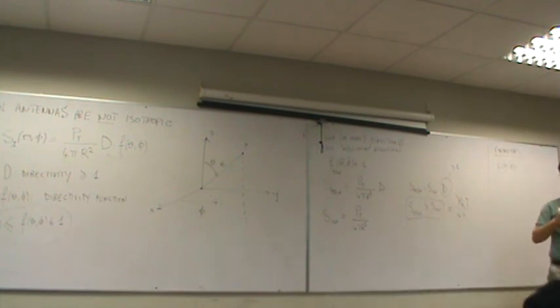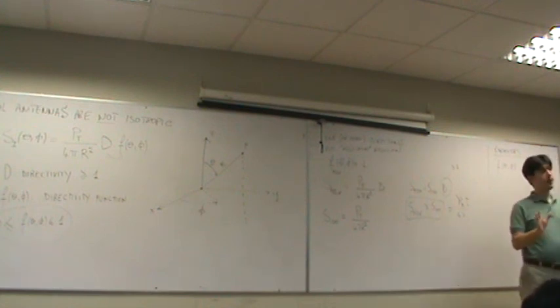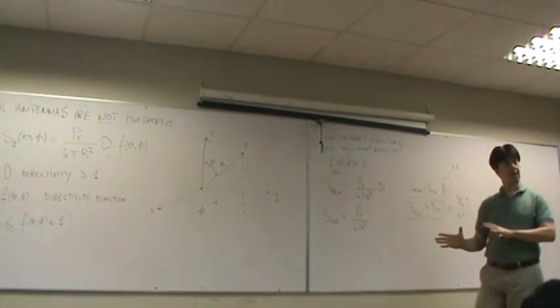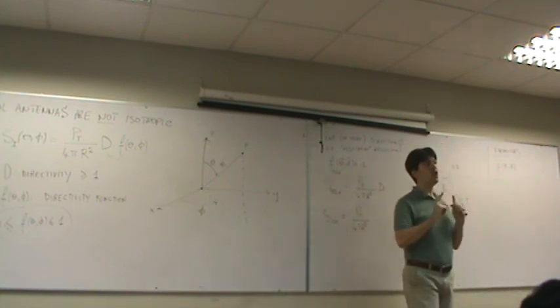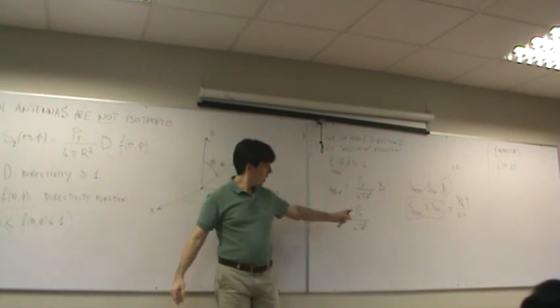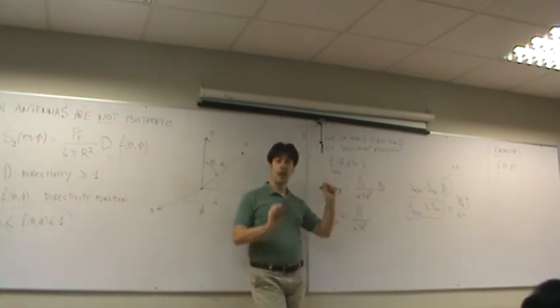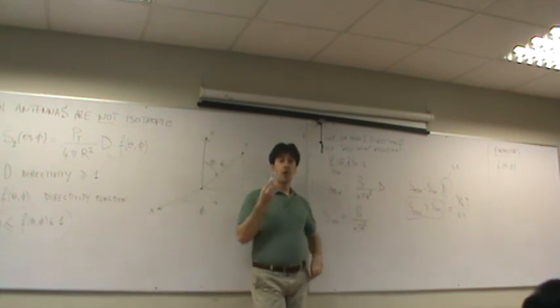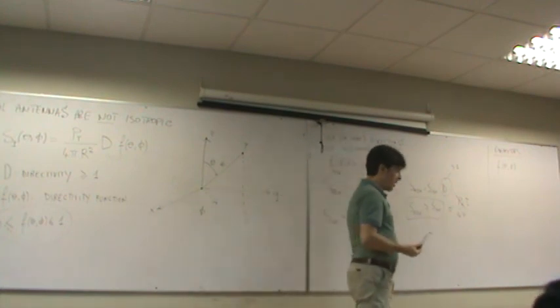You have to think about the directivity function. You have to think about the way you want the antenna to radiate. And the gain is what you can get. You cannot choose gain and directivity function independently, because the two things are strictly related by that precise equation.